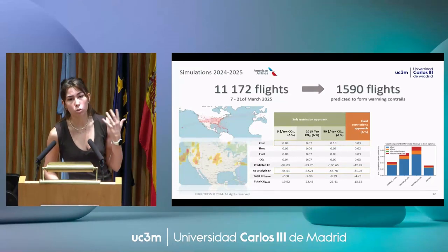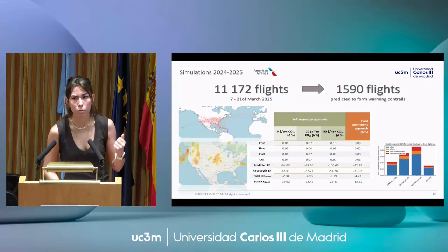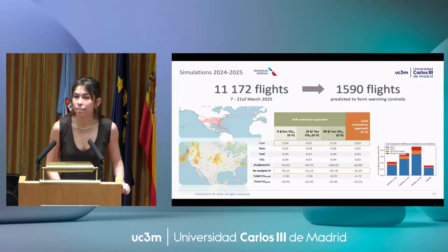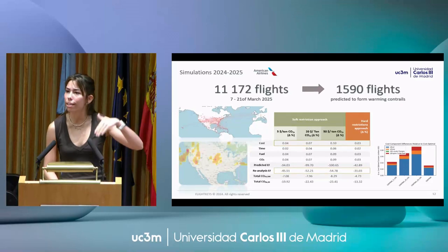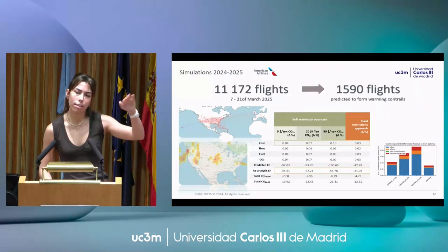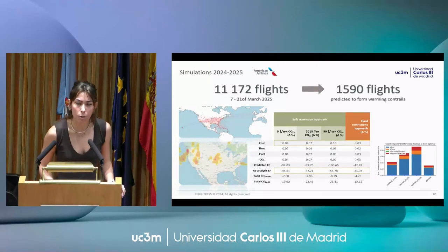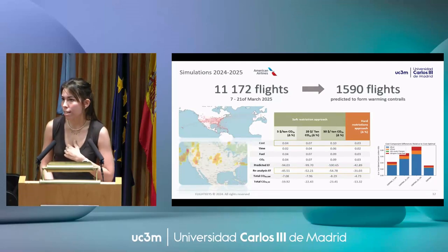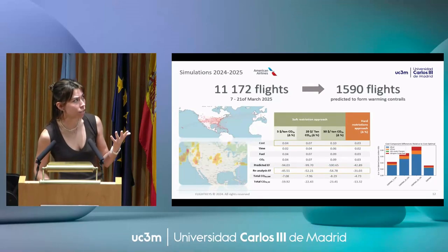that the biggest source of cost increase comes from fuel, followed by time, and then engine cycle cost. This is through the increasing and decreasing, the yo-yo flights that they called. Whenever you increase and go down and increase and go down the flight level, that puts the engine in higher thrust settings, and that leads to increase in engine cycle cost.